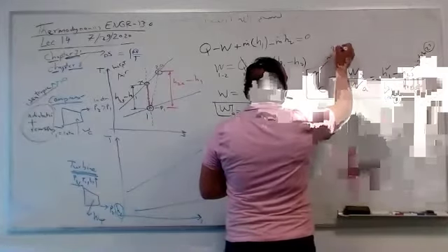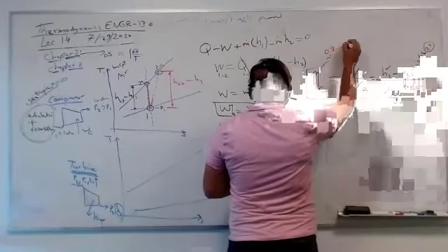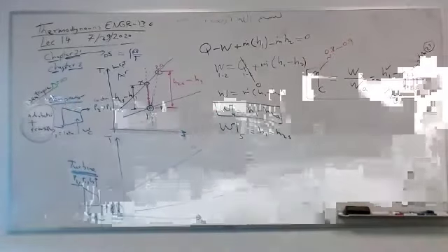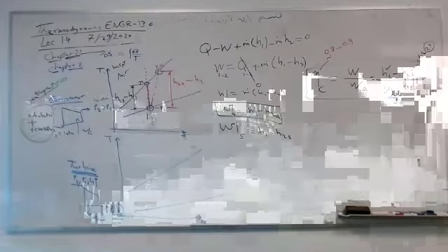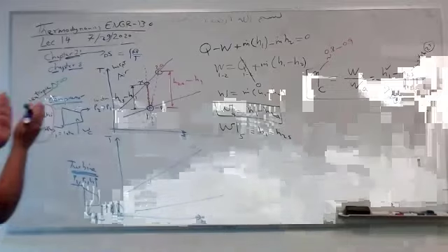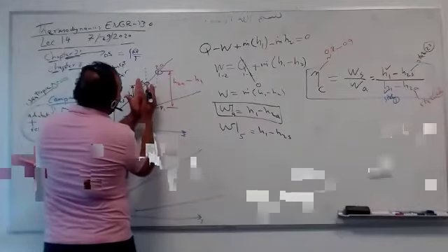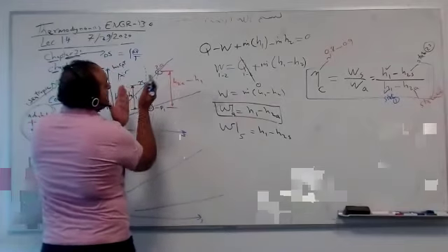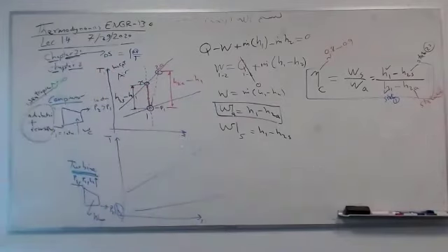So typically, compressor efficiency is like 0.8, 80%, up to 0.9. This is the typical range. It can go to 0.92, a little bit higher, but this is the typical range for compressor efficiency. We wish to go vertically, but we have a little bit of slope with 80%, 85%, 90%, 95% sometimes. If it's a very, very good compressor, it can go to 92, 95. Okay, guys?